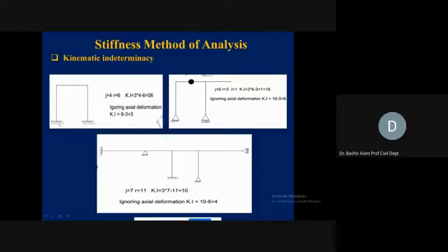So here we can say easily that its kinematic indeterminacy at this support is equal to 0. The bottom right support joint also gives you 0 degree kinematic indeterminacy. Top left 3 degrees, and this top right also gives you 3, because those are free rigid joints. So 3 plus 3, it means it is a 6 degrees indeterminate problem. Or you can go by the equation. What was the equation? 3j minus r is equal to the total indeterminacy.